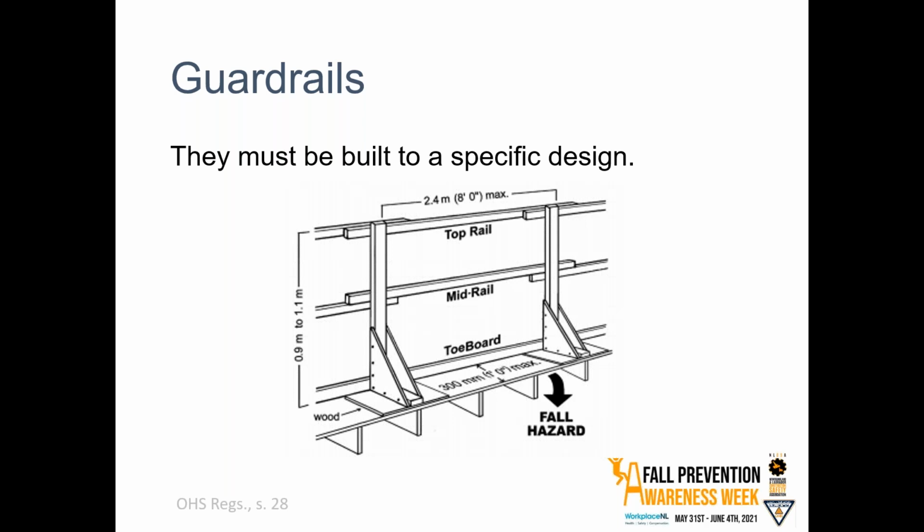If the rail is too low, there's a potential that if someone comes up to it, it could hit them in a part of their body where their center of gravity could cause them to fall over the rail. So there is some science and engineering behind this spec. And I think I've maybe talked that to death, so we'll move on.